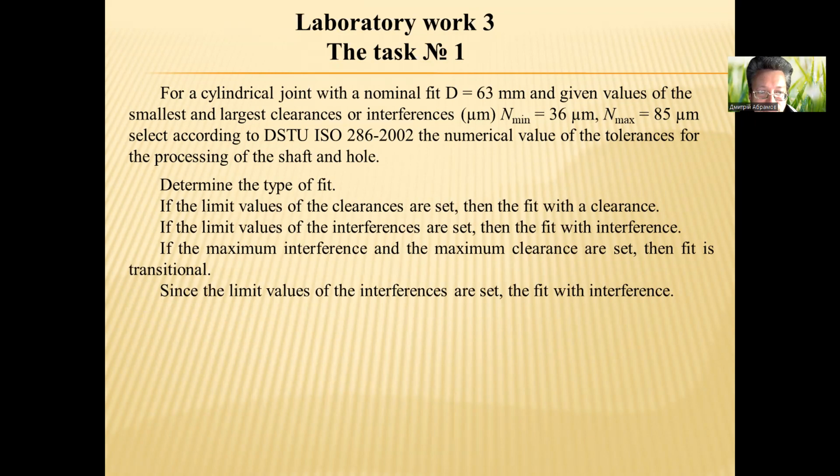If the limit values of the clearances are set, then it is a fit with clearance. If the limit values of the interferences are set, then it is a fit with interference. If the maximum interference and the maximum clearance are set, then the fit is transitional.